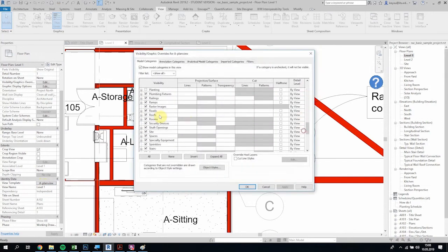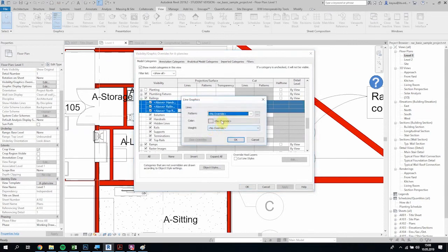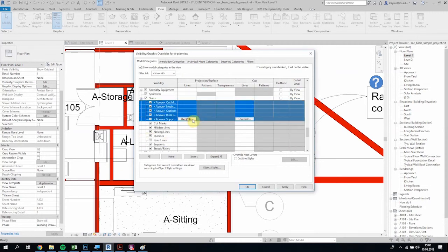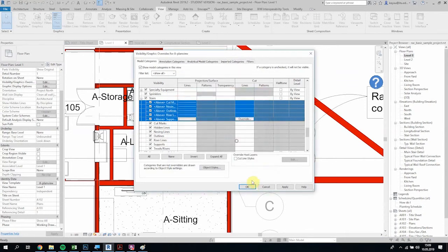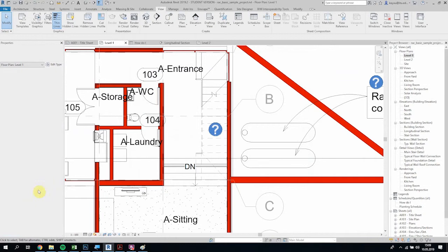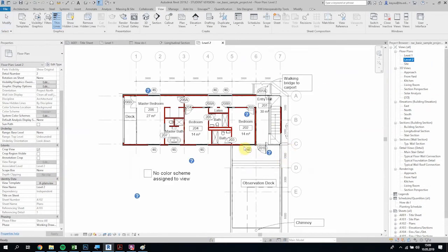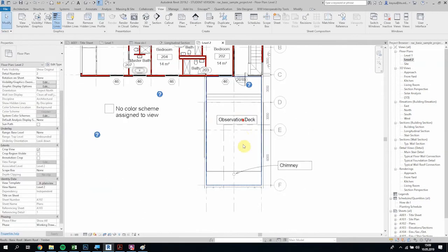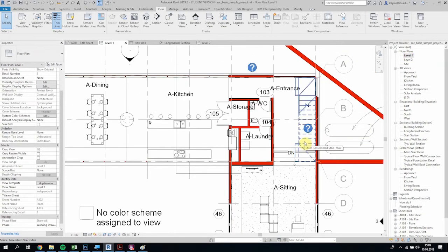Here when you change the railings and stairs in the view template, it also changes in level 2. In level 2, we don't have above stairs, so it changes automatically in here, but we can't see any differences because there is no such view here.